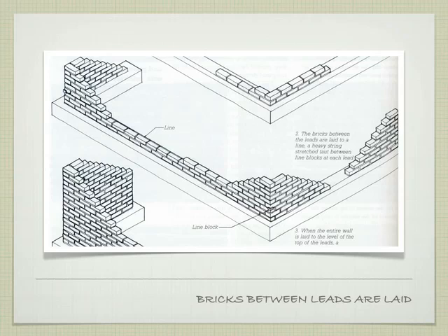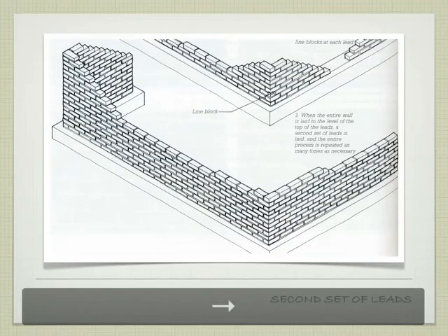Then a second course, and we work our way up, right, in kind of a triangular pyramid pattern on the corner, right? And then we string a line, right, from one corner across to the other corner, which allows us to lay all of the stretchers along here, right, at all the same level, right? So as long as we make sure our leads are correctly made and are correctly level, right, filling in between them becomes really easy, right, which is the idea.